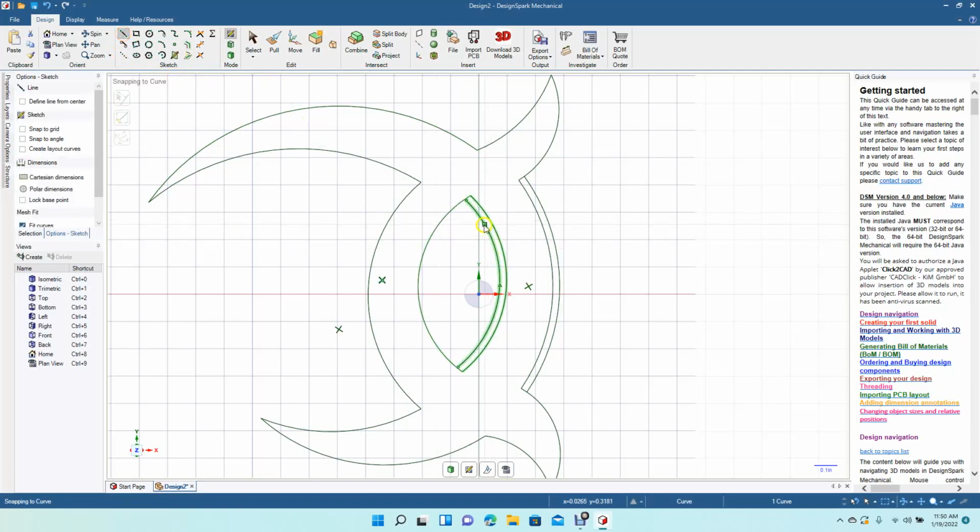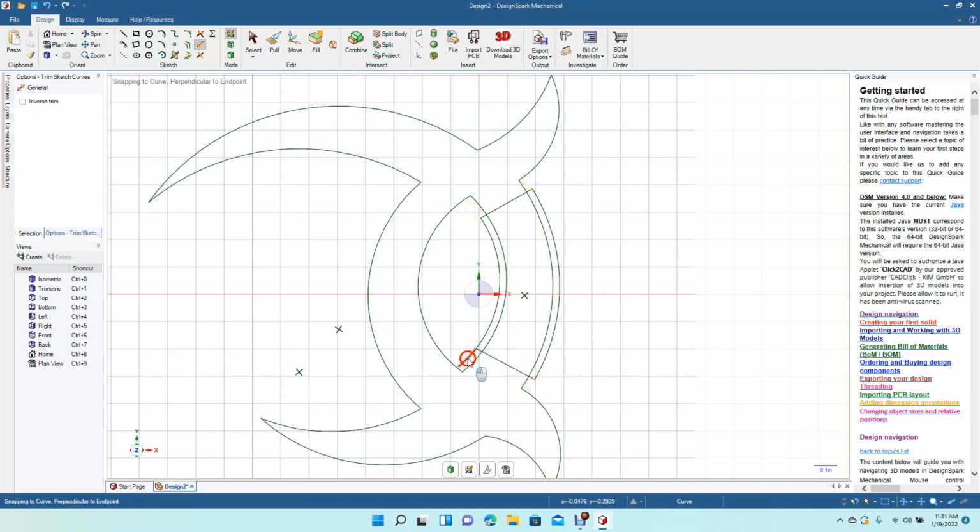Now we'll grab our line. We're going to go from about this point here, right there, straight across. That's going to represent our handle. We'll get this line tool, and then we'll go from that point straight across. Okay, now we're going to grab our trim away tool. Let's get some of this stuff. Don't need it. Okay, and then trim away that piece and that piece. So we're going to extrude this, and all the other stuff's going to be extruded as well.